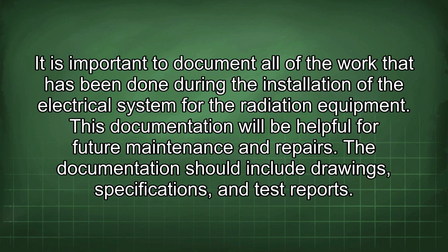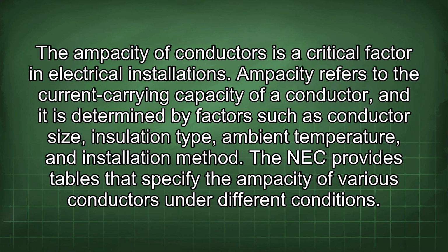The documentation should include drawings, specifications, and test reports. The ampacity of conductors is a critical factor in electrical installations. Ampacity refers to the current carrying capacity of a conductor, and it is determined by factors such as conductor size, insulation type, ambient temperature, and installation method.